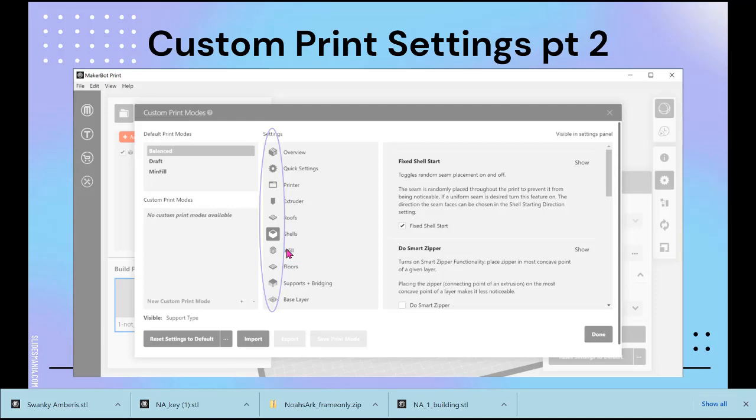And you maybe saw on the slide earlier that making that infill any higher than 60% really doesn't make it much stronger, believe it or not. And as far as shells go, if you get up to 5 or 6 shells, that's really the maximum you're ever going to need. So you can go in here and adjust the shells and infill.